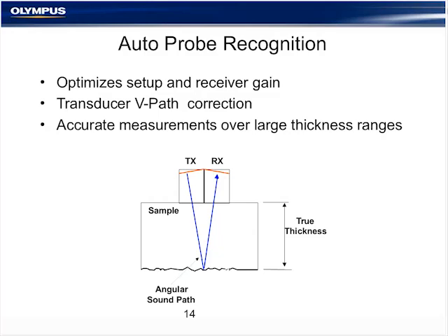And that's kind of what we're showing here in this diagram. If I get my faux laser pointer here. Any dual probe, or certainly most dual probes, are constructed with two crystals, a transmit and a receive, that have what we call a roof angle. Due to this roof angle, the sound travels through the delay of the dual probe and enters the part at a very small angle, typically just a few degrees. What this does is it gives a type of focus to the sound. For a backwall surface that's pitted or very rough and corroded, a very uneven surface, this can help quite a bit with sensitivity when the sound reflects more focused off of a small pit and then is received back on the receive channel.